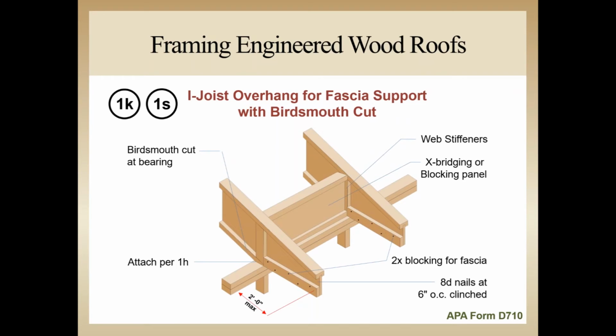When using the bird's mouth cut details, the outside corner of the blocking panels may need to be trimmed so they do not extend over the top edge of the rafters. This trimming is allowed in this case.